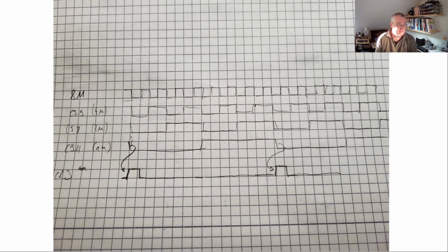But as you can see, when 1 megahertz goes down, which is later than this 8 megahertz going down because of the ripple effect, the JK flip-flop goes up. And when the JK flip-flop is up and the 8 megahertz clock is up, then this NAND triggers and puts that signal down again. And this is the signal that actually loads the shift register.